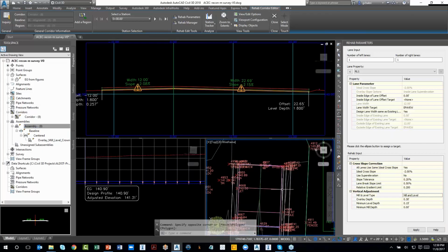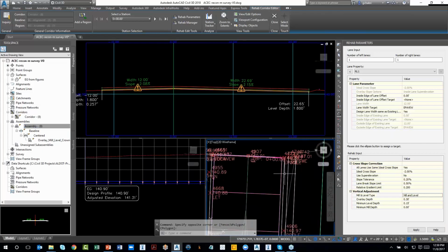So this is exactly the same thing, right? I have a curb section here and then a sidewalk in this example. So I took the inside edge of that curb to the inside edge of the curb, and I did a best fit alignment here. I could have chosen the best fit alignment many ways, but I chose the existing CP. But the profile now I can smoothen it.